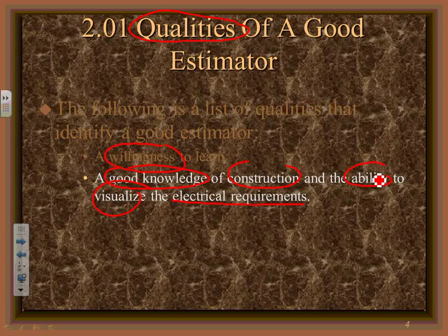The more you know, Derek and Karen, the more you will be a better estimator, because estimating a conduit that's going through a beam, you're not supposed to go through a beam, or if it's going to go through a concrete wall, is completely different than estimating the same conduit if it's going to go through a sheetrock wall. You guys agree with me? The amount of work that you estimate for this piece of conduit.